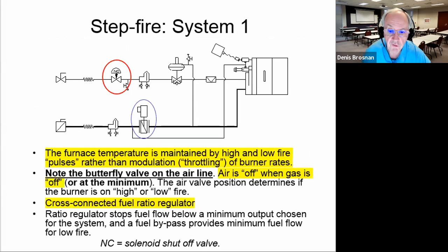So here's the control system. The gas line is on top, feeding the burner. Here's a ratio regulator in this system. This slide was supplied to me by some good North American people, a trim valve. That's their symbol for a little manometer device. That's their trim valve symbol, and the gas is going into the system.